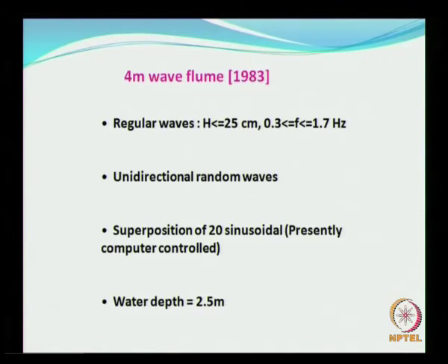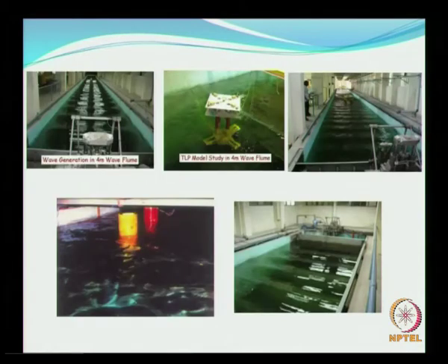Here the water depth is around 2.5 meters. These are some of the tests that have been carried out. So you look at the wave flume, this is now 90 meters long. So you see the wave maker here 4 meters wide, and you have 2 meters deep. These two are views of the flume, and here you see a tension leg platform being subjected to waves.